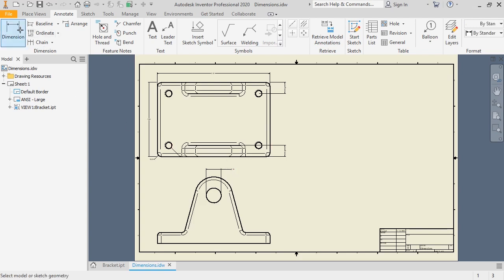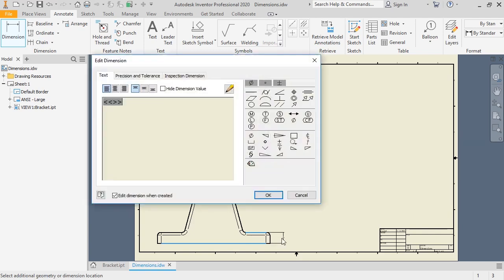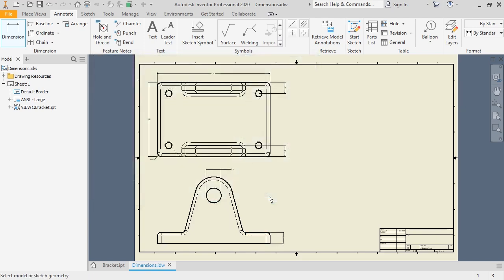This tool works the same way as the Dimension tool used when making sketches in a 3D part model. Just click on an item you want to dimension, and the tool adds the appropriate dimension type. The Retrieve Dimension tool can save you some time, but you'll often need to use the Manual Dimension tool to detail your 2D drawings appropriately. This is because you may have incorporated a particular dimension scheme in your 3D part to give it a specific design intent for controlling the 3D model, but that may not be the best dimensioning scheme for a 2D drawing. A good dimensioning scheme for proper 3D design intent might lead to tolerance stackups or poor inspection dimensions when you try to use them on your 2D drawing.